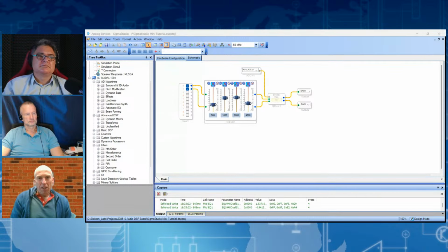So in that case, you don't have to do any DSP programming, and the DSP program to do that is included in the Arduino library. So that's one thing. You can also, before outputting the audio, make the DSP do something to the signal as well, add an effect to it. That's one possibility. You can also use the DSP to sample audio and send it to the ESP. Then the ESP can process it and send it back to the DSP, or the ESP can send it over Wi-Fi or ESP-NOW or over Bluetooth to something else. All this is possible.